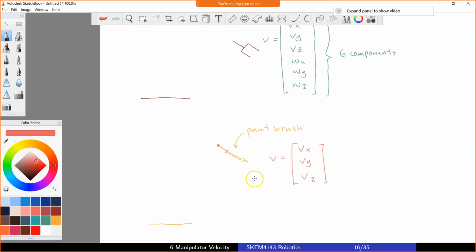So if you have a flat surface only on the floor, this is the canvas that you want to draw on, right? Probably you only require the end effector, which is a paintbrush, to move only in x, y, and z direction or motions. So if this is the case, you only need a robot arm which has 3 degree of freedom.